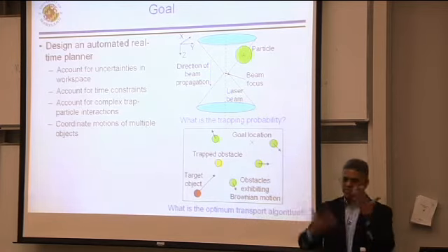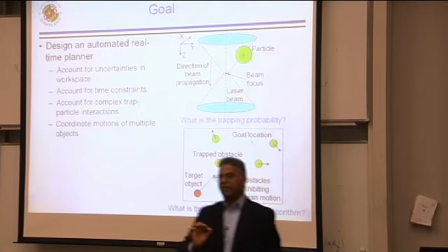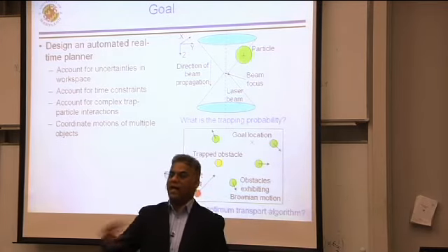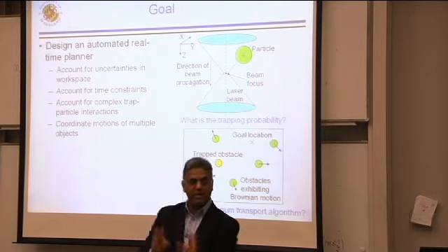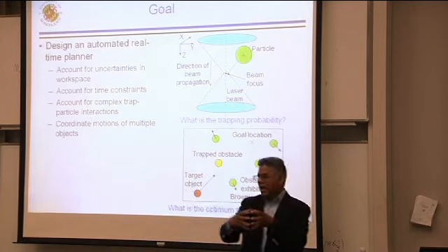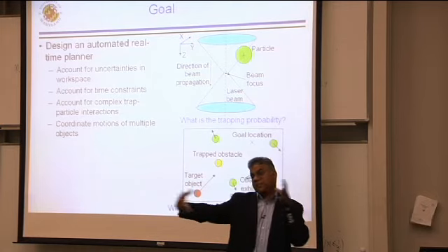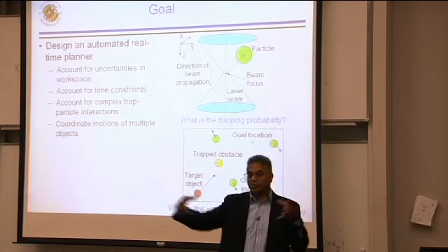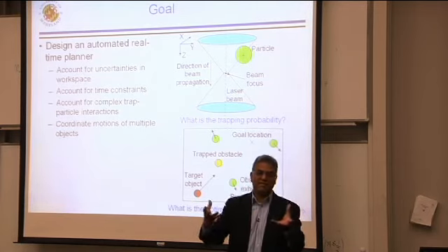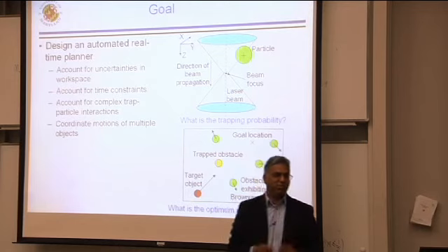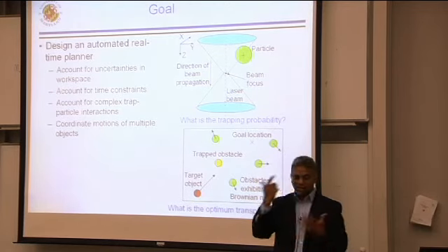So there are all those complicated trade-offs, and this is a real-time operation, meaning that you have a 20 millisecond window to plan your next move. That's it. Whatever you do, you fit within the 20 millisecond window. So you have to choose the right level of representation, because if you create a grid-based representation which is too sparse, you get lousy plans. If it is too dense, you don't meet your 20 millisecond window, because the stochastic dynamic programming takes too long.